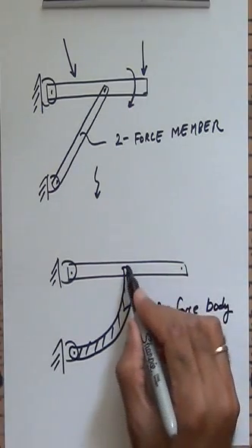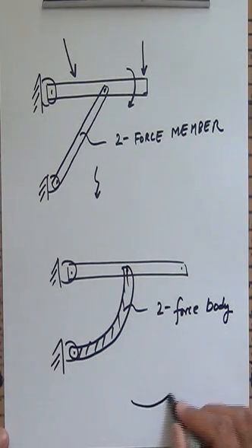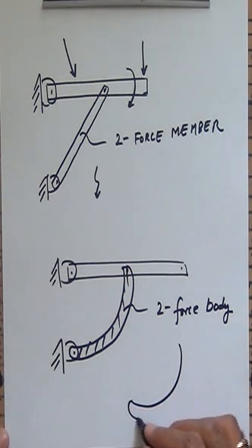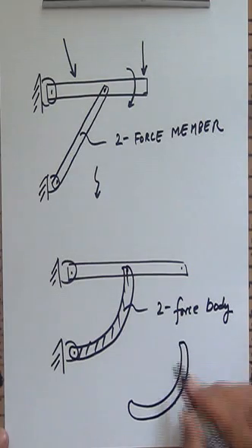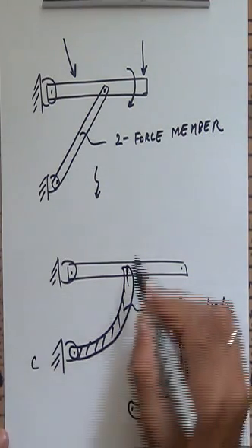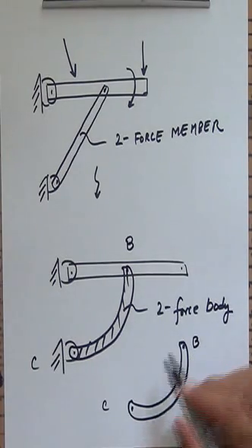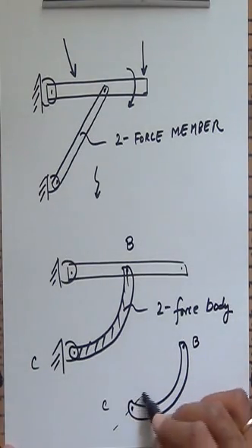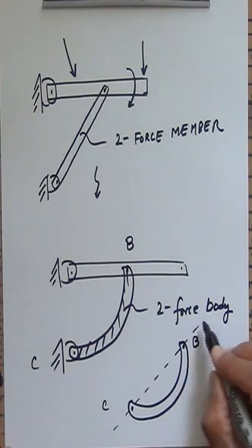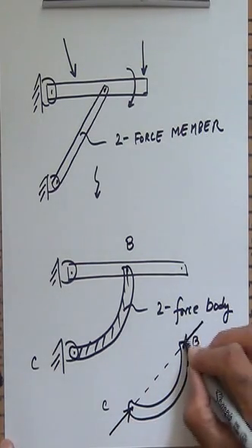And they're pinned together here. I can take this body and draw it in the following form, whatever that form is, and I know that since there are forces acting at only 2 points, let's call this C and this B, all I have to do is join a straight line and connect these 2 points, and I know that the force is going to be along that line.